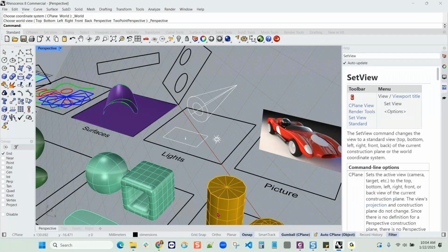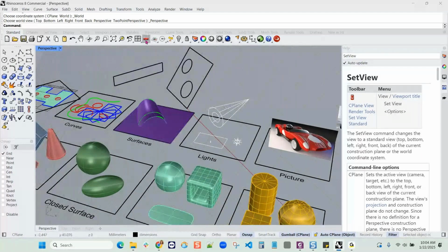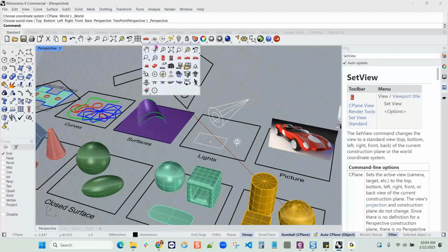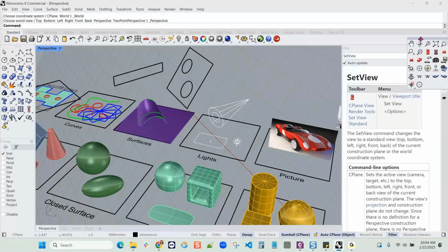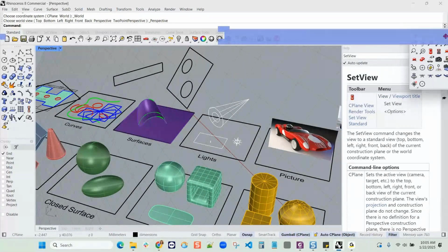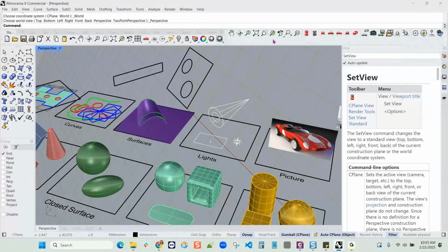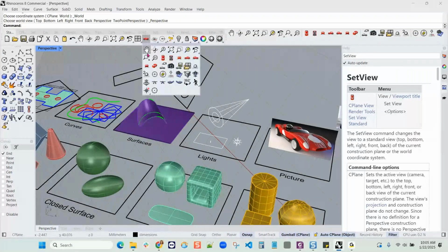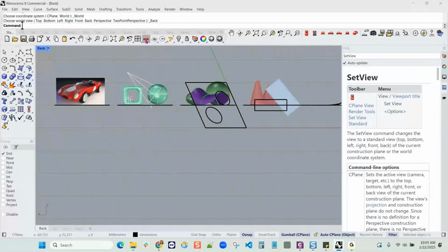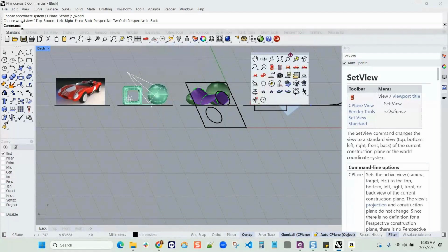And you can also return to the perspective view by pulling off this toolbar. And if you have room over here, you can dock it. Set it down first and then dock it. And I pulled it off from here. So I pressed and dragged, grabbed the bar and moved it away.